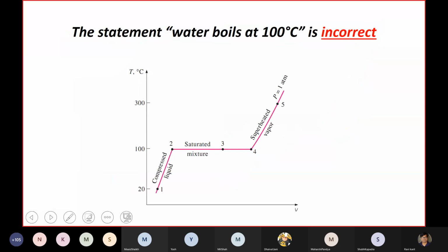Now this is the last statement I want to put, and then I will switch to the EES software to get these values. In EES software, whenever I type some temperature 100 and some pressure 90 kilopascal, I'll get all the fluid properties H, S, V, or any other properties.